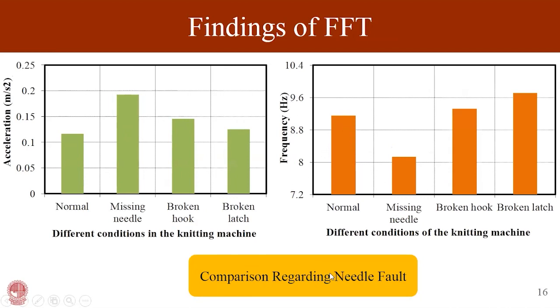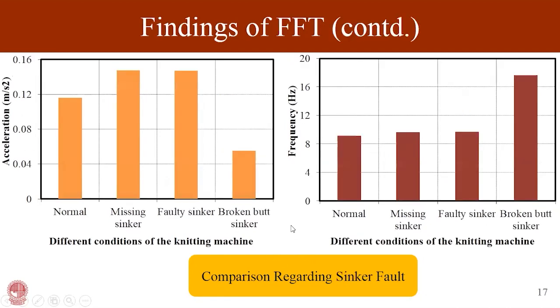Now, firstly, we are talking about the needle faults. It's the same case in terms of sinker faults. You can see in the sinker faults that the vibration amplitude also changes during different faults, and the vibration frequency also changes during different sinker faults. So from this analysis, I can actually say that the vibration does change and vary during the different faults.